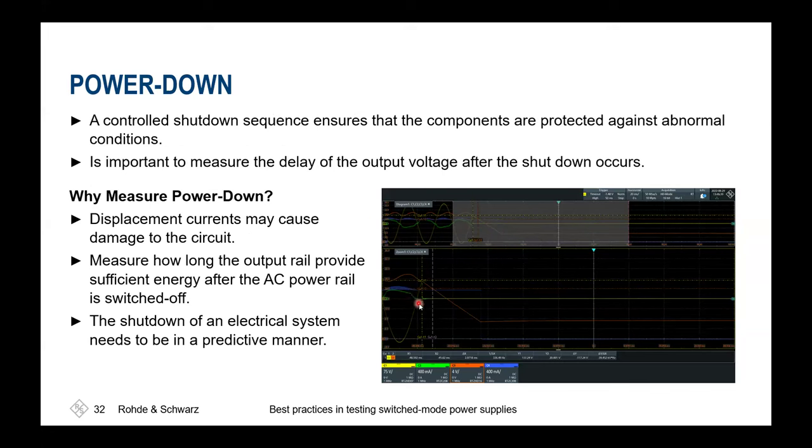If you think about an inductor and you'd like to cut off the power at such an inductor immediately, this would cause a lot of ringing and headaches afterwards. That's why it's very important to power down in a certain order, to ensure that all power that you have to get rid of first is gone, and thus it's unable to resonate in your system.